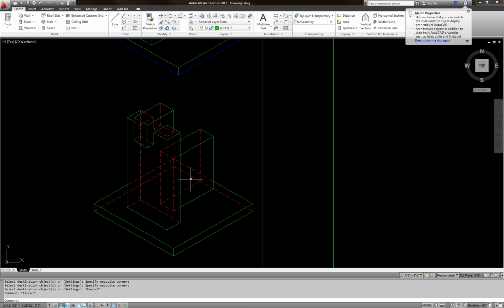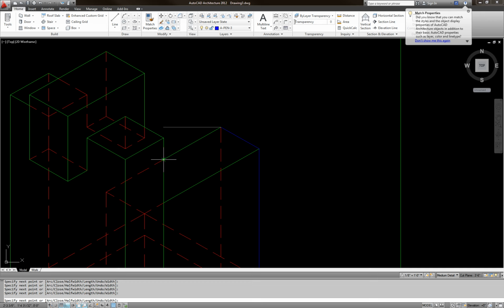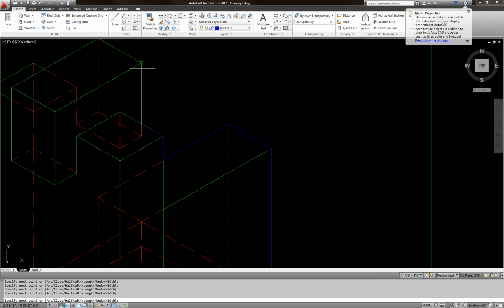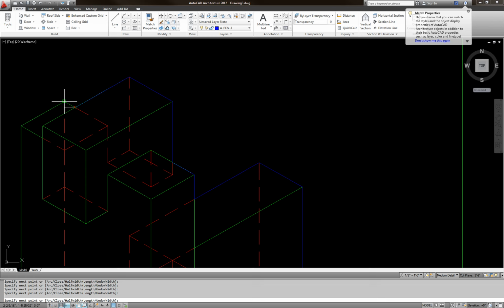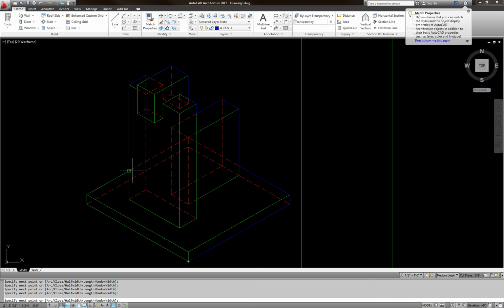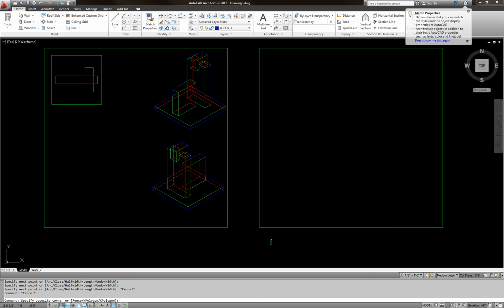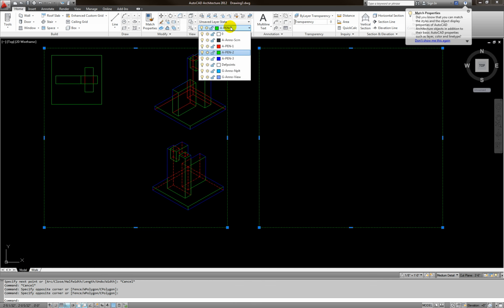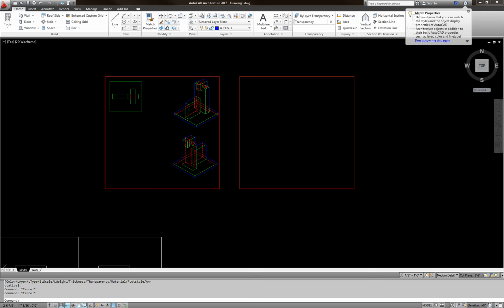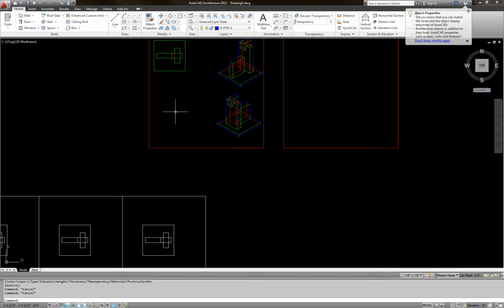Okay, now it's good. Now I'm going to take my pen, click on the blue, PL enter, polyline. I'm going to start from this corner at the bottom, and I'm going to go all around this. Make sure that you click on the midpoint and the endpoint, and I'm clicking all around my object. Practice guys, practice. Okay, so now that's my whole thing. Now I'm going to take this rectangle and put it on red color, so it'll print very lightly. Okay, so that is for isometric.